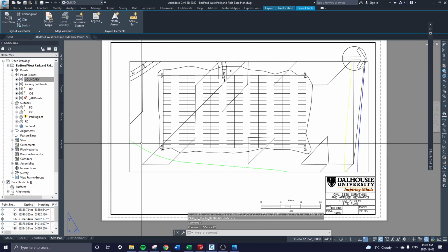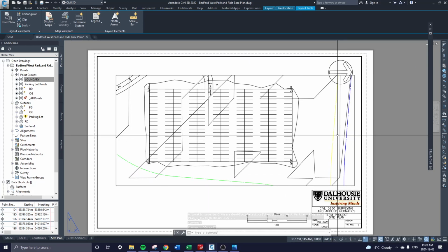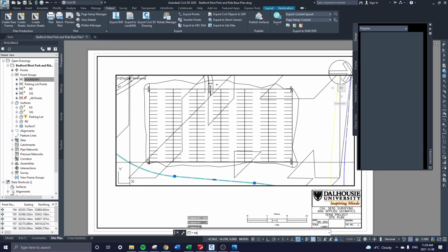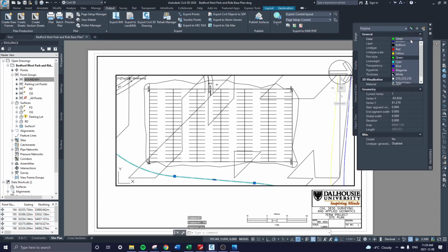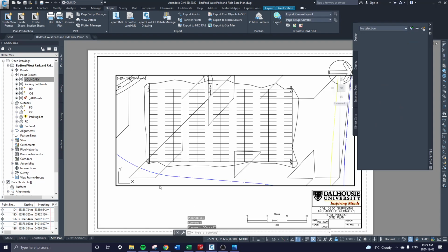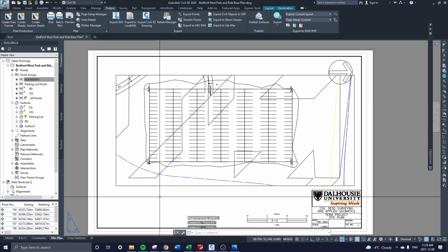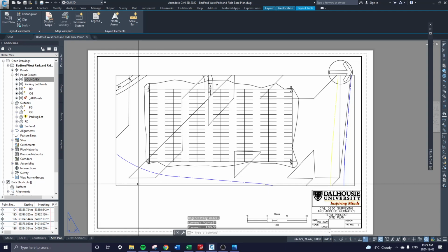So you can see I have green lines. Those are going to print in green. And Paul might not like that. So you might need to adjust your coloring if that's the case. To do that, go to your properties. You might just have to put it by layer. That's still blue. Regen? No? Okay. Well, we'll have to play around with that. Anything else?